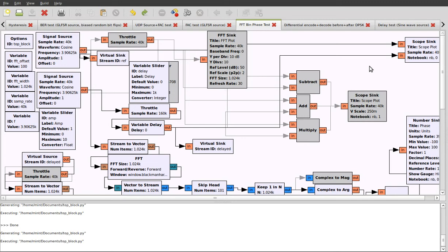The objective is to find the phase difference between these 2 signals, between the 2 sine waves, and if we were operating with idealized constraints such that they were the same frequency and the same amplitude, you could do some arithmetic trickery to try and derive the phase. However, here we're operating with broader constraints, and the requirement should be that the input signal can be anything, and we just want to focus on one particular frequency of interest.